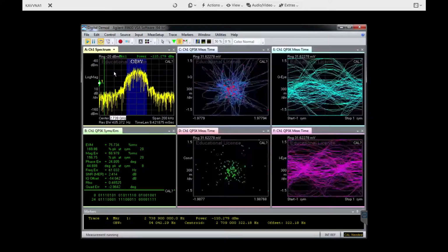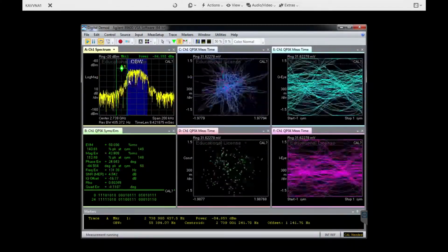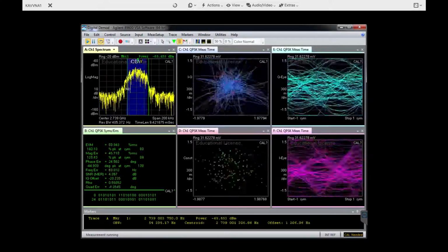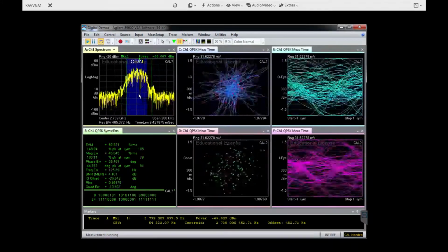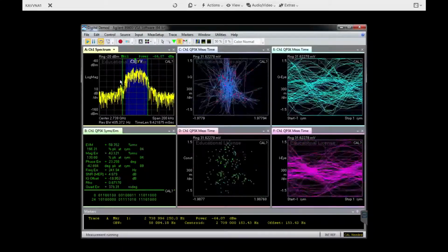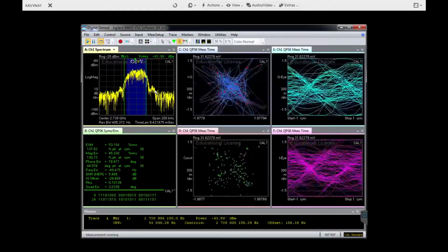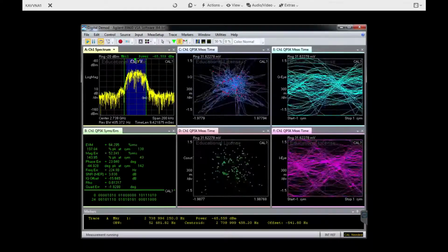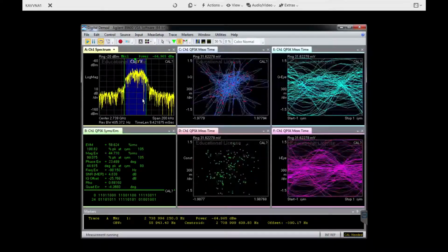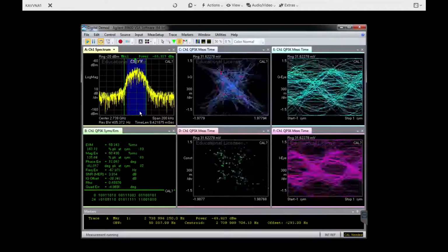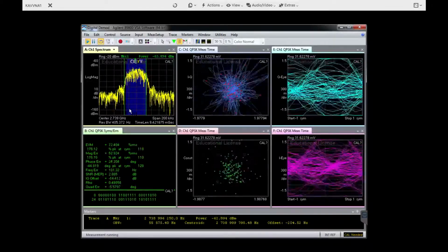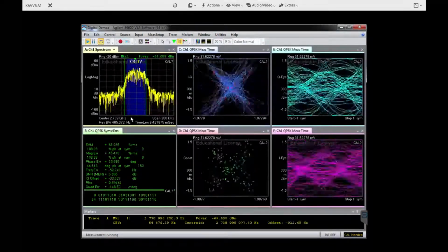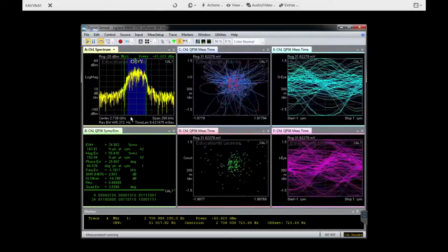So you can see here also we are receiving another signal here. So you will repeat this procedure for -10 dBm, and you will comment on the differences when we are using and not using the LNA, as you are supposed to do.